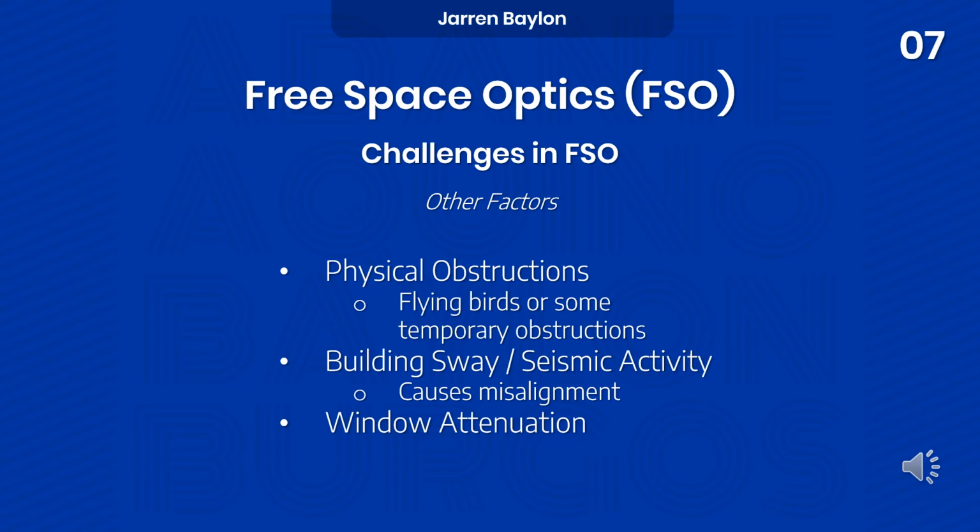Lastly, we have the window attenuation. In some cases, where high altitude rooftop weather losses are more, FSO systems are installed in windows. But it has been observed that uncoated glass attenuates almost 4% of signal per surface due to reflection. Tinted or insulated windows can have much greater attenuation. So, a trade-off between those two options, the window or rooftop installation, should be achieved.